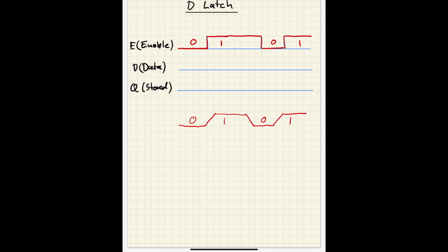For example here, when the value changes from 0 to 1, then this takes a while until you actually reach the 1. There are always so-called delays involved. And during this change from 0 to 1, you have states of the logic gate which are undefined in a Boolean sense. But we will come back to that in another video where we actually deal with delays. So for now, let's simplify it as I drew it before.